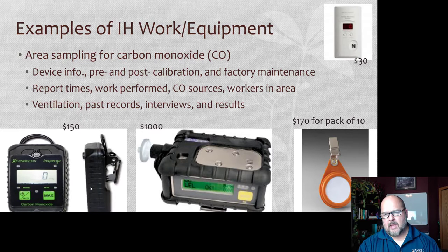I know Nighthawk, I think, has a certain level at which it'll start alarming. What you really should do if you get that is get out of the house. You should open doors, open windows, shut off gas systems, and make sure everybody's okay. Every year people die from carbon monoxide poisoning. It may be a propane heater that wasn't well ventilated, maybe a furnace or a hot water heater where the exhaust port was blocked or something, and it builds up.